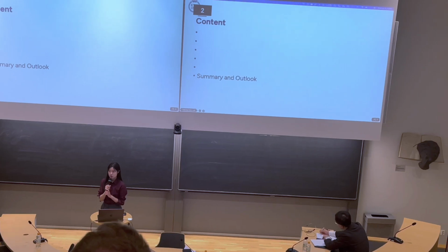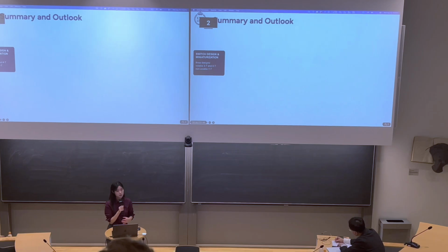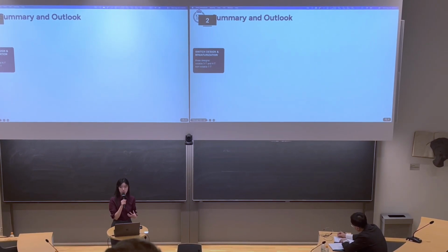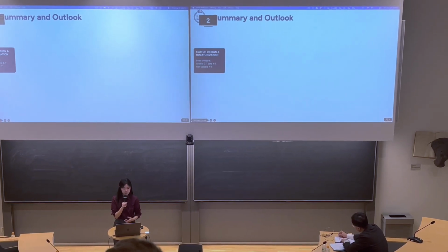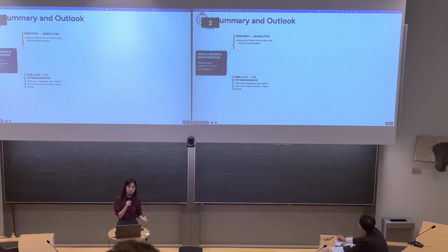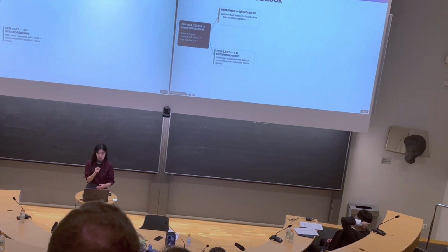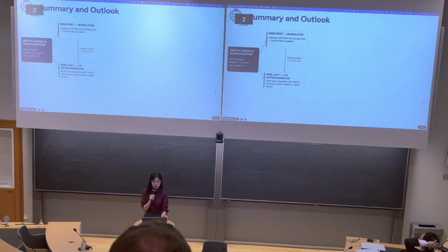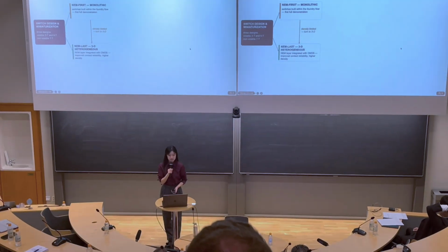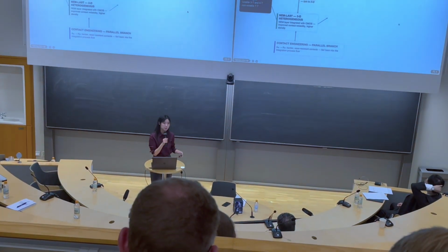And we finally come to the summary and outlook. So in this work, we first designed the miniaturization and optimization of the NEM switches for 3T, 4T, and 7T configurations. And based on these designs, we implemented 2 different integration strategies, the NEM-first monolithic integration and the NEM-plus heterogeneous integration. And the second integration approach can give us a much better routing density through the vertical stack. In between, we also investigated the contact material and the contact shape for the NEM switches.